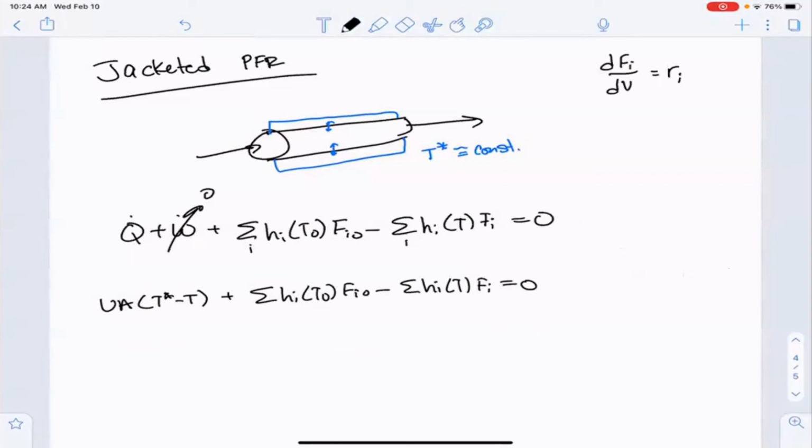In the area? Exactly. And we just looked at that even in our previous example, right? That we used the reactor volume to calculate the area. So that's correct. So what's normally done here is that for different shapes, we define a shape factor, a lowercase a, that's just defined as delta A over delta V. Now for a cylinder, a is just equal to 4 over the diameter. And you could use the equations we used a minute ago to determine that.